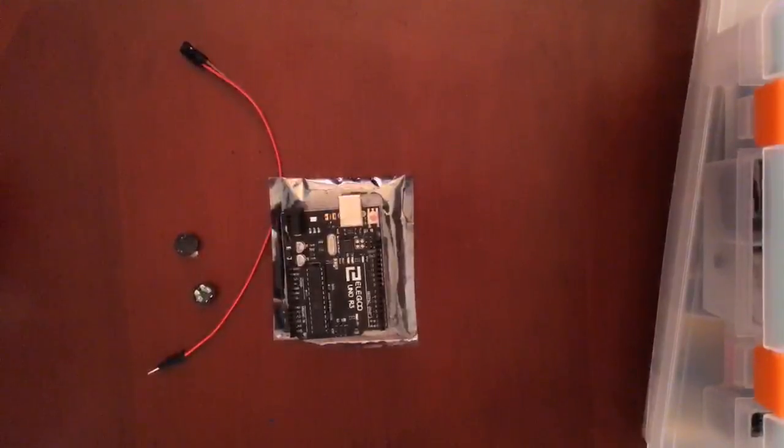The difference between the two is that an active buzzer has a built-in oscillating source, so it will generate a sound when electrified. A passive buzzer does not have such a source, so it will not tweet if DC signals are used. Instead, you need to use square waves whose frequency is between 2K and 5K to drive it. The active buzzer is often more expensive than the passive one because of multiple built-in oscillating circuits.